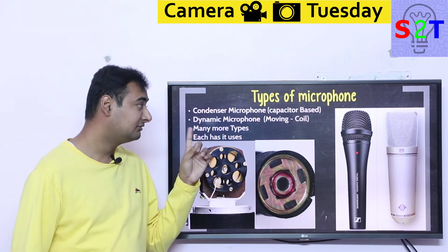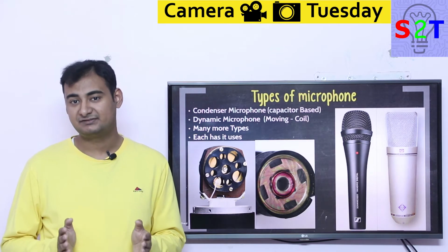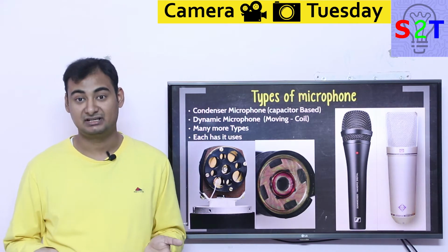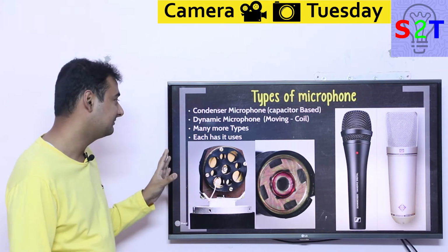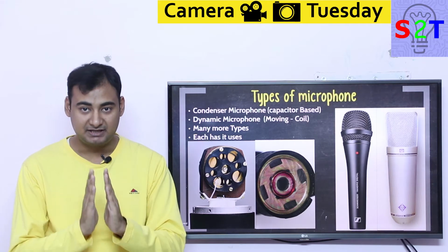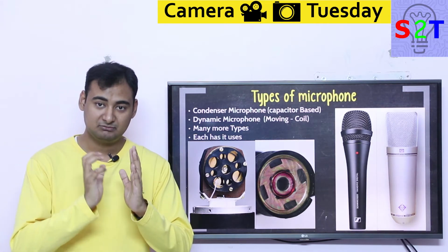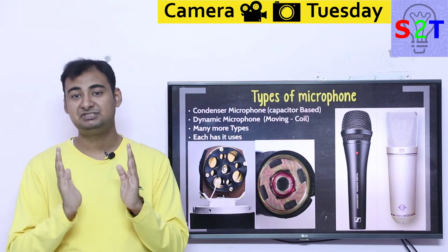First is the condenser microphone, which is basically capacitor based. If you are not familiar with a capacitor, you must have seen the capacitor drawing in your science book. It's basically 2 plates. When somebody talks about a condenser microphone, that's what they are referring to: 2 plates with a capacitive charge. When air makes it vibrate, one will be fixed, another will be flexible. That flexible one will change the signal.